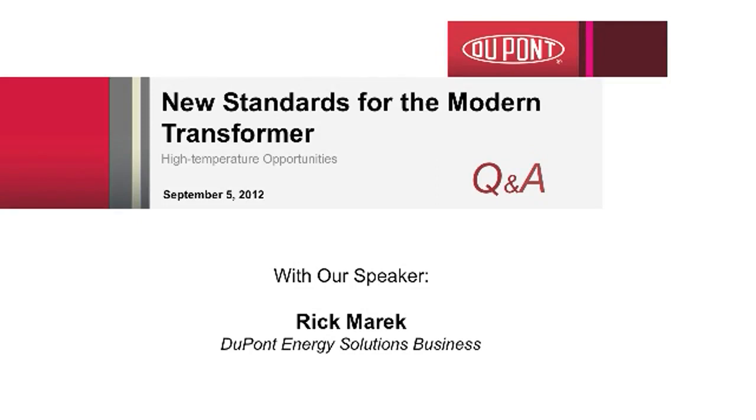You have to look at your application and then decide. The typical ester, FR3, is more expensive than mineral oil. So it depends on your cost issues as well. So very difficult and no general answer to that question.